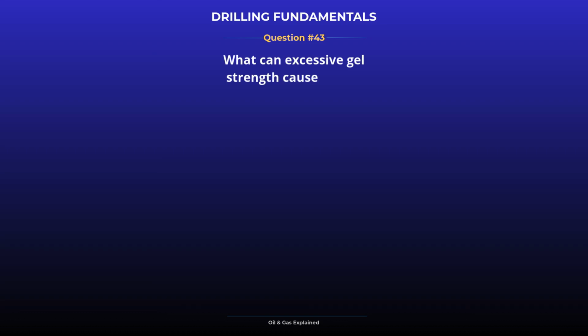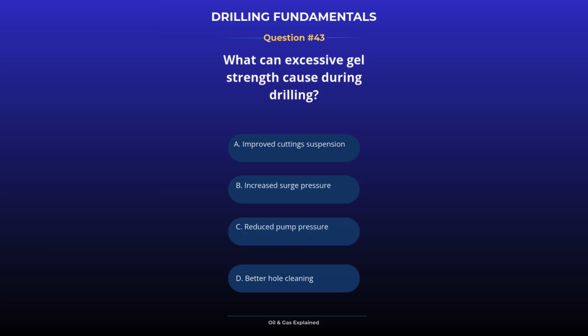What can excessive gel strength cause during drilling? High gel strength increases surge pressures, raising the risk of formation fracture.